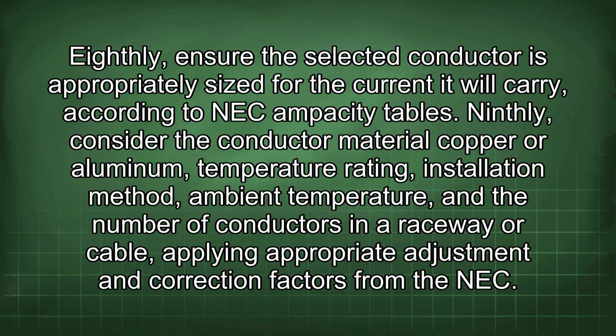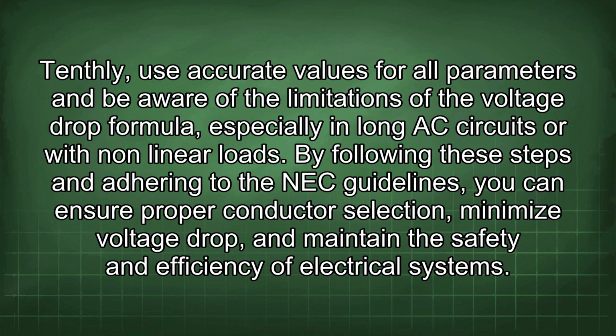tables. Ninthly, consider the conductor material, copper or aluminum, temperature rating, installation method, ambient temperature, and the number of conductors in a raceway or cable, applying appropriate adjustment and correction factors from the NEC. Tenthly, use accurate values for all parameters and be aware of the limitations of the voltage drop formula, especially in long AC circuits or with nonlinear loads. By following these steps and adhering to the NEC guidelines, you can ensure proper conductor selection, minimize voltage drop, and maintain the safety and efficiency of electrical systems.